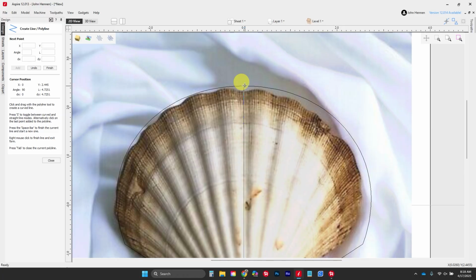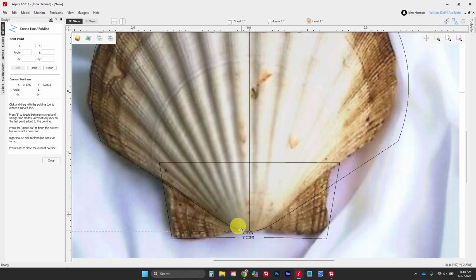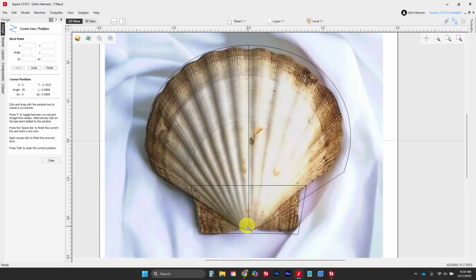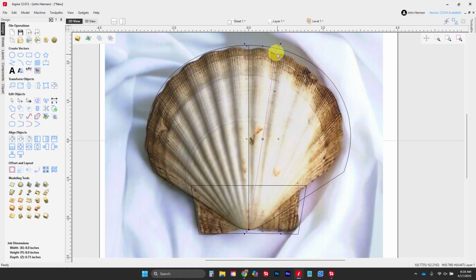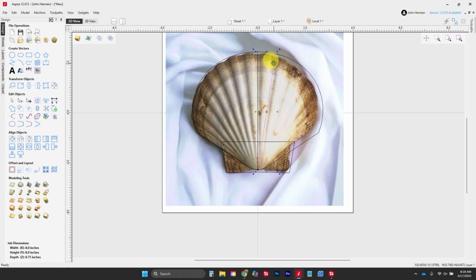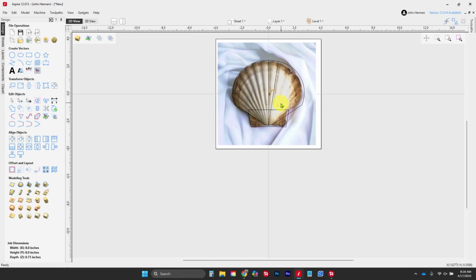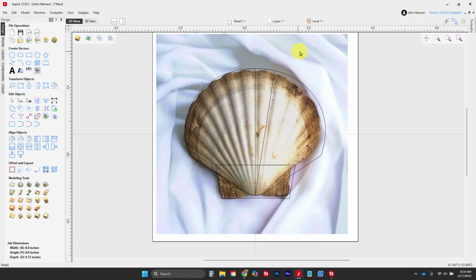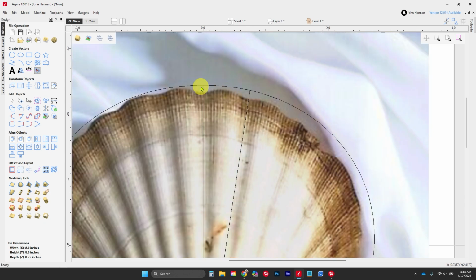So we're going to end that line right there, hit our space bar, come back down, grab that same point, and we're going to come up into the center of the next ripple here. And what we're looking for here is a shape that we can create. We're going to do a 2-rail sweep, and it's going to come from the bottom up and back down. So let's go ahead now and build our 2-rail sweep. Our 2-rail sweep starts by just drawing a polyline. What we want to find is the distance here before we start.